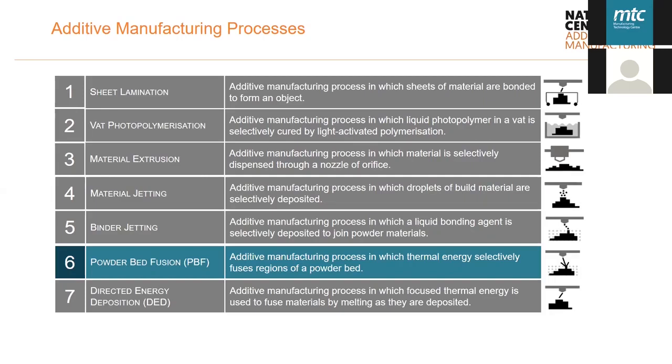I'll take this one if you want. Yeah, sure. From a polymer point of view, go on. Yeah, I think that was in relation to most of the polymer ones that pointed out limitations in mechanical properties. You're right that the layering aspect of additive manufacturing does have an impact on this. So your Z strength, as the part is built in Z, in many cases will be lower than in the XY plane. This is most certainly the case with material extrusion. But that doesn't mean that you can't achieve good mechanical properties. It's just that for the most common materials, you are a bit more limited.